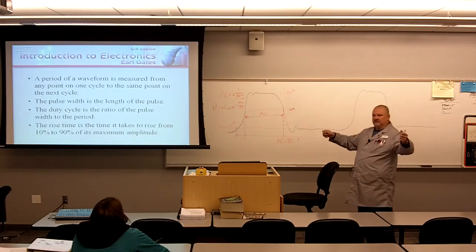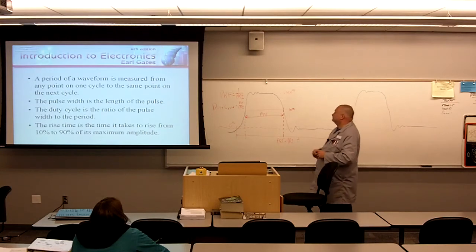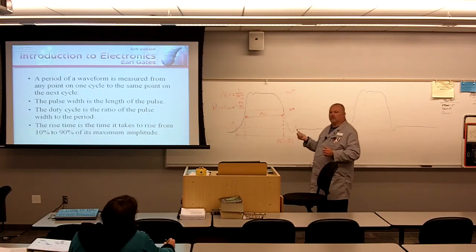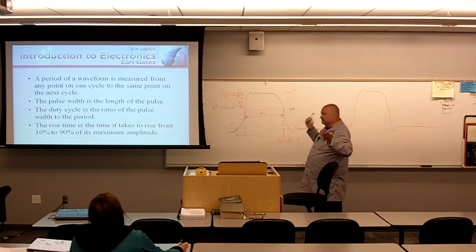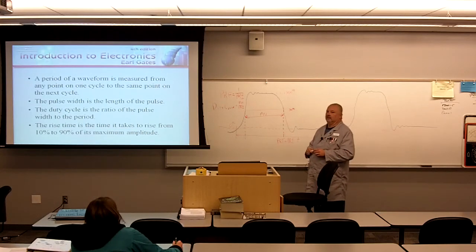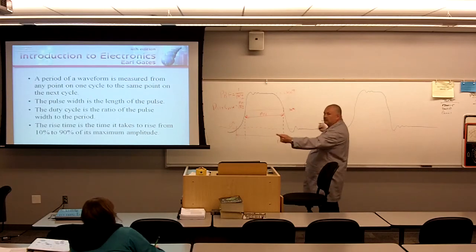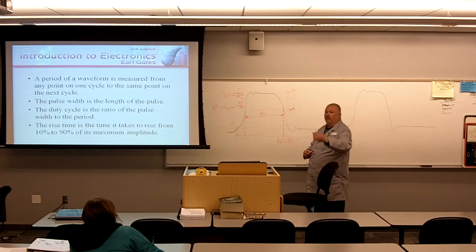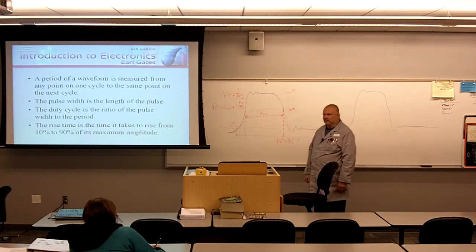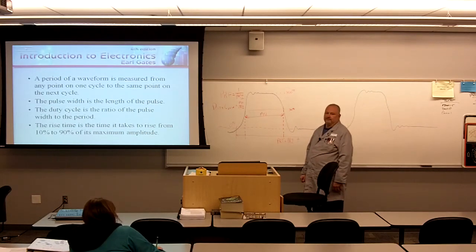I was using that just as a reference. So what would the duty cycle of this be approximately? If it's on for 20 inches and the total cycle is 60 inches, 1/3, very good. So this would have a duty cycle of approximately 33 1/3%.